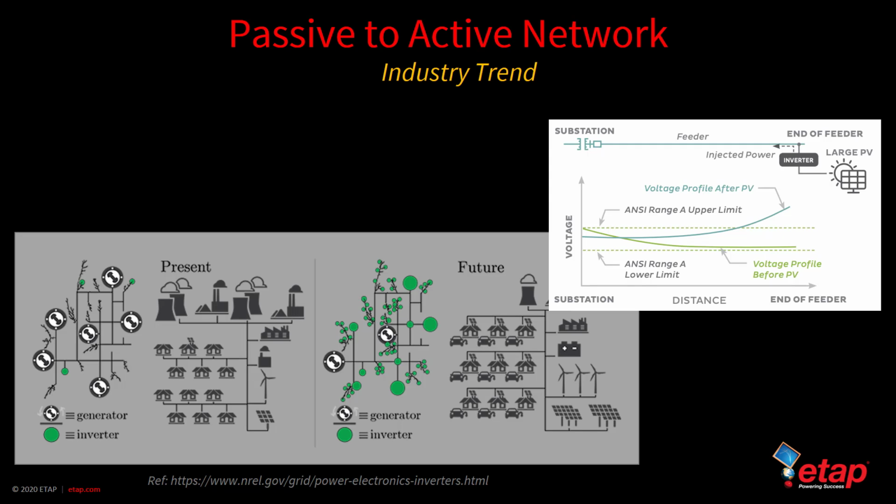For example, during and after a disruption of the grid, variations in voltage and frequency may occur. Historically, PV systems have been required to immediately disconnect when these conditions were detected. However, if a large amount of DER capacity disconnects at once, this could further destabilize the grid.